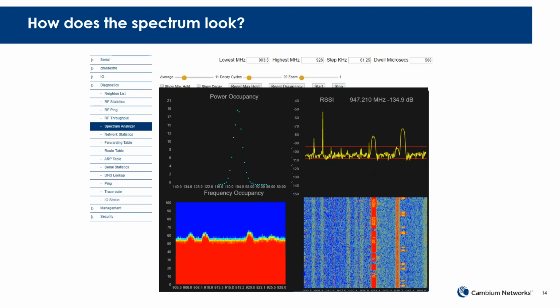And then on the left side, you'll see frequency hopping, and you would expect to see the general noise floor from an ISM band. That's what the charts on the left show, which frequencies are being used most often, and what the overall power occupancy is. So I can start to get a sense of the load on an ISM band, particularly in 900 megahertz. I can see how much of the time that band is being consumed by the transmitters in the area. So it's a nice tool. It's all well documented in the user guide, and it's definitely worth having a look at. It's a great troubleshooting tool that we now have at our hands.